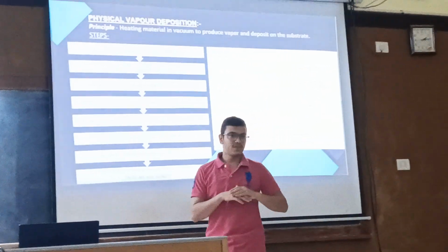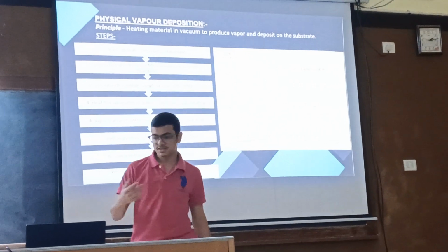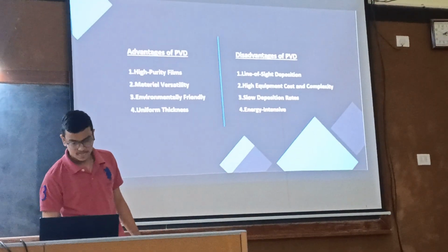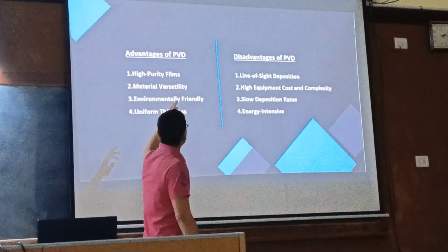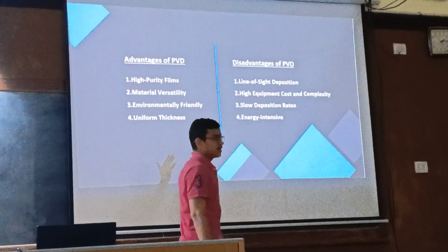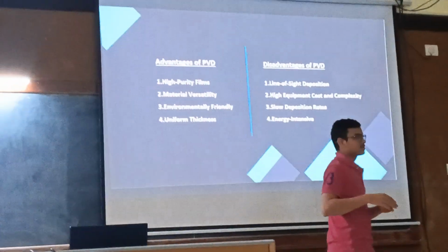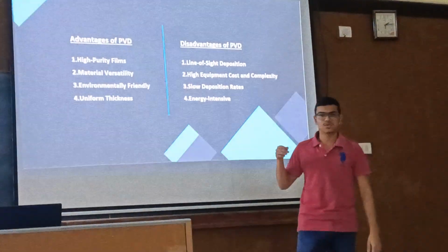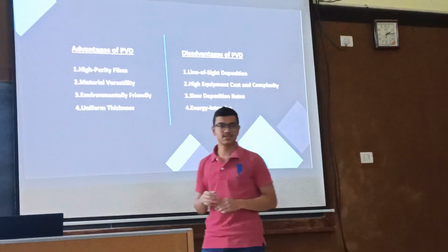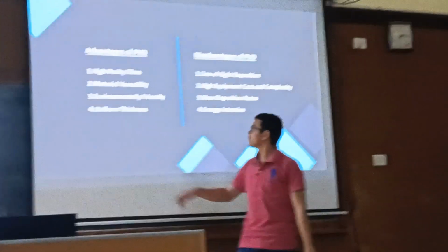Now we are done with our thin film deposition. Next, I have listed some advantages and disadvantages of PVD. PVD is done inside a vacuum chamber, so the purity of the thin film is high.